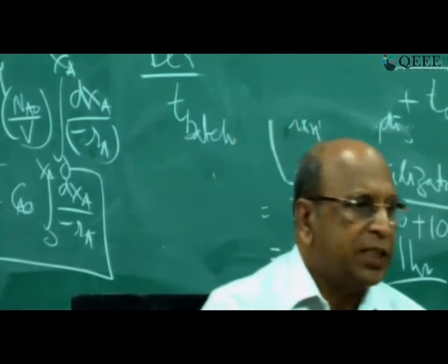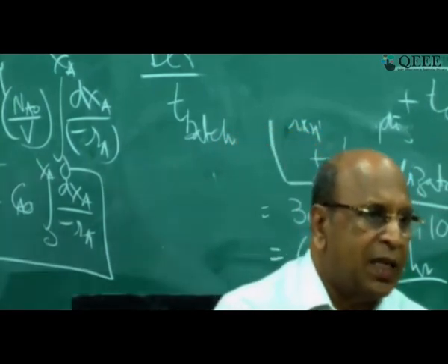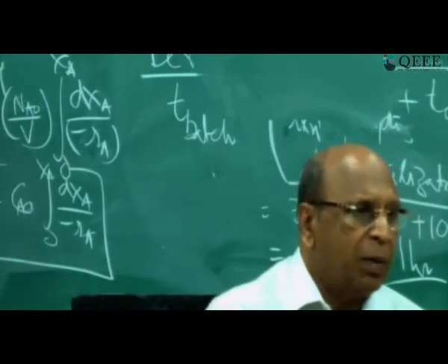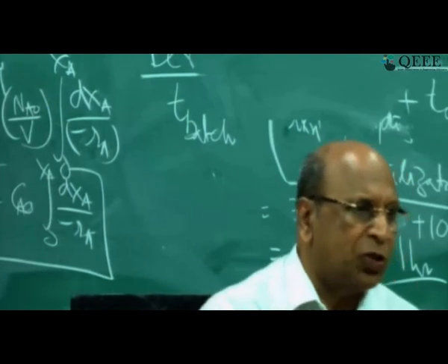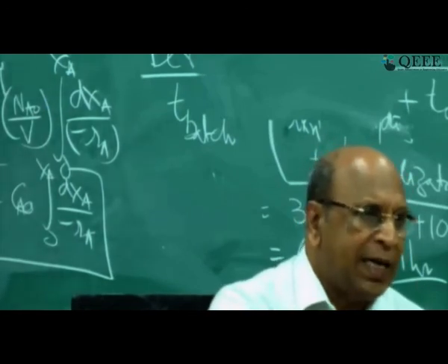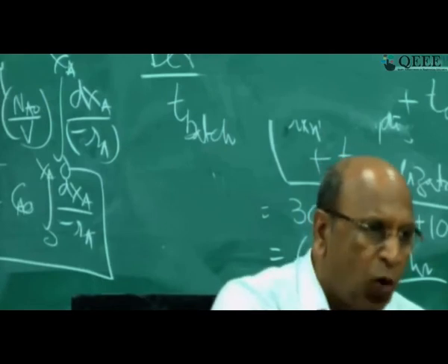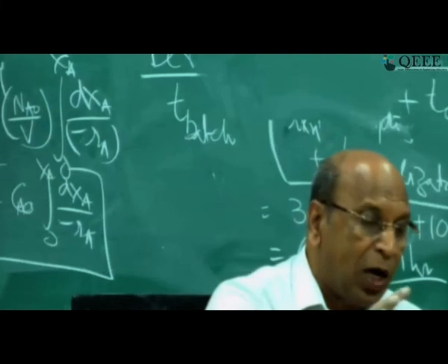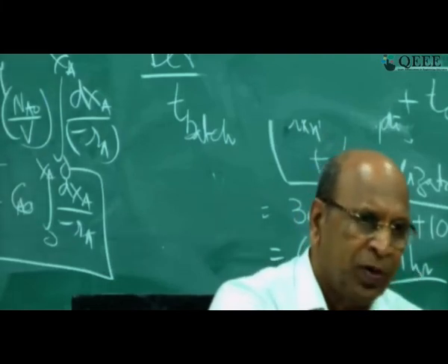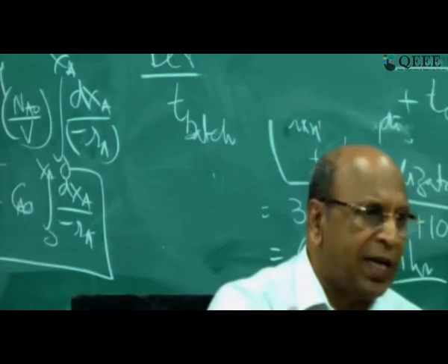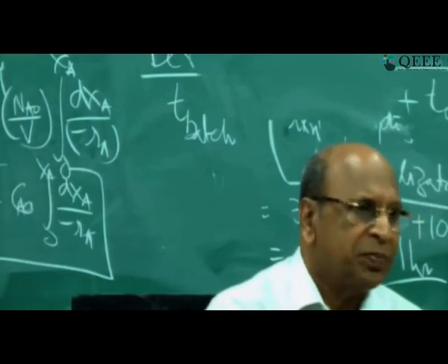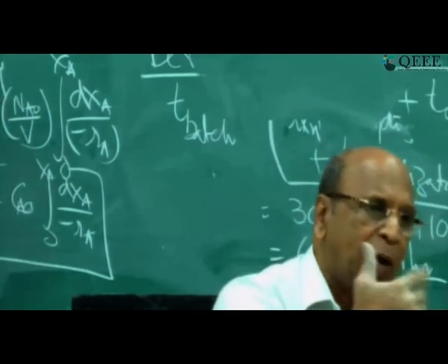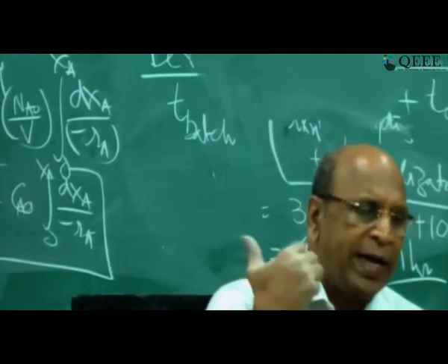I think again this is a good question. Does reactor type selection affect the conversion? Yes. If you take batch reactor, anyway that is different than continuous reactor. If you take plug flow reactor and mixed flow reactor, for a given volume, definitely the conversion will be different. If you take 1 meter cubed of plug flow reactor, 1 meter cubed of mixed flow reactor, definitely you will have the difference. The conversion generally is high for plug flow reactors. That I will tell you tomorrow, why it is high.